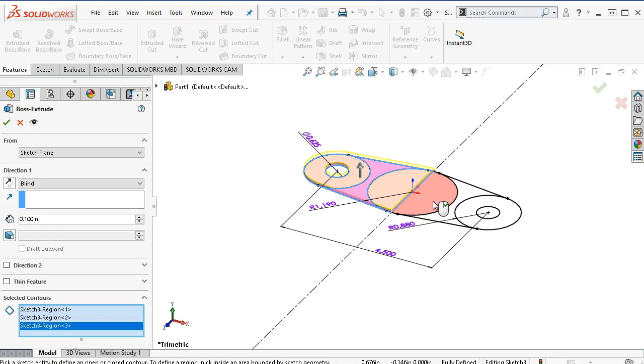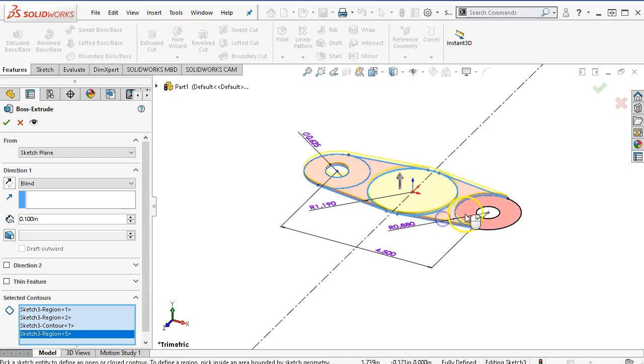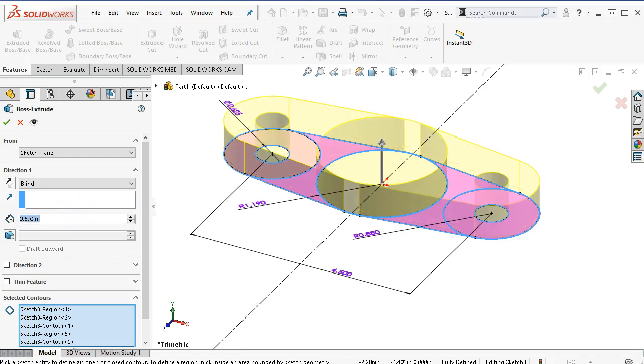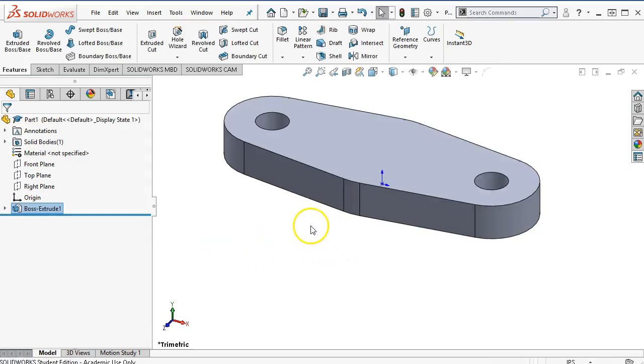And it does use the center line. So in that case, if I went to the contour and picked the circle, then region, then region. So on the end region, this would be one of those instances where, since it closes off the hole, that's not the preferred. We want to leave that hole open and participating in the extrude. At 6.9, get our extrude. Now we have the choices to make.